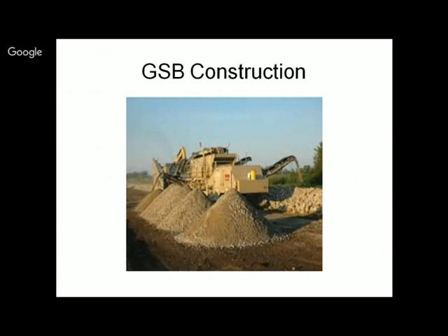you need to find out the loose quantity of GSB material in per kilometer length or maybe per 100 meter or whatsoever is convenient. तो मान लीजिए पर किलोमीटर में मुझे इसकी लूज क्वांटिटी पता चल गई, तो आपने लेंथ ले लिया, उसका विड्थ ले लिया, मल्टीप्लाई किया तो एरिया आ गया, उसकी थिकनेस से मल्टीप्लाई किया तो वॉल्यूम आ गया, और जो लूज बल्क डेंसिटी से अगर आप मल्टीप्लाई करेंगे तो आपको उसकी रिक्वायरमेंट इन केजी आ जाएगी and you can convert it in terms of the volume.